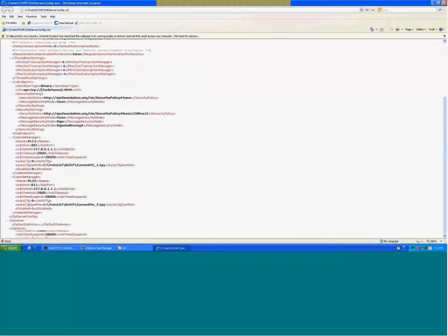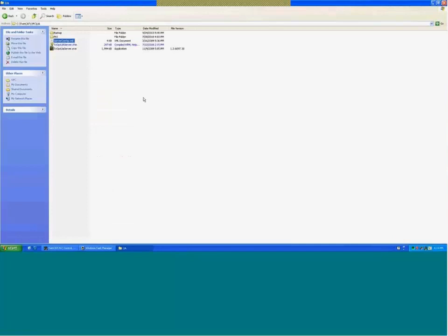For instance, what will be the URL? What are the supported security policies? So none on OPC UA, you can encrypt if you want, you can sign and encrypt. You may require certificates for the communication, so it's way more secure than the regular OPC DA communication. And you enable which PLC you're going to communicate with, so you can go and edit this XML file to have the OPC UA configuration.